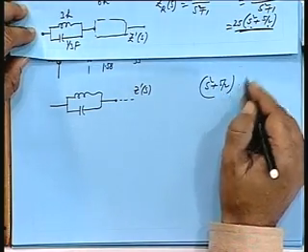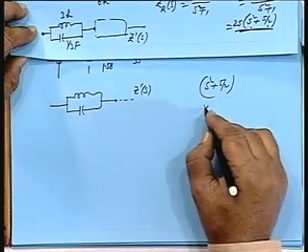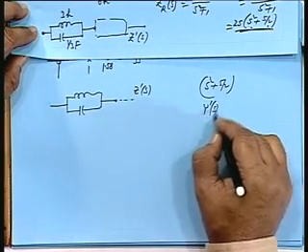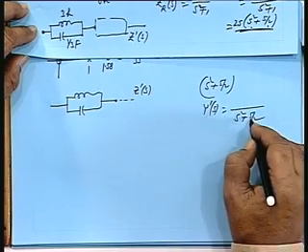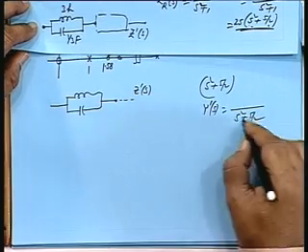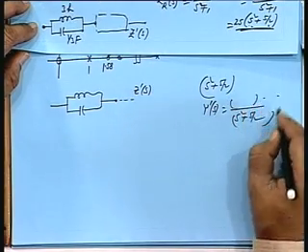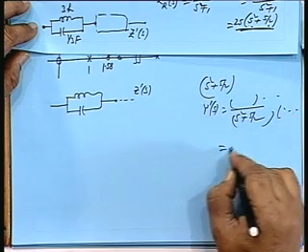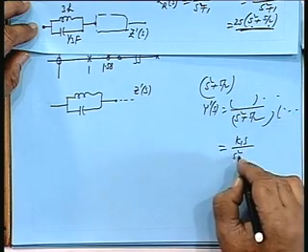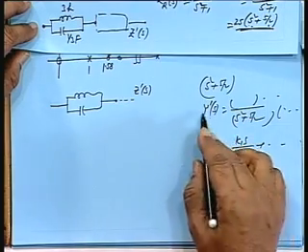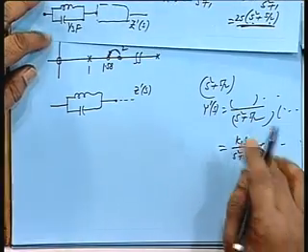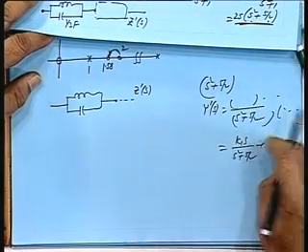Any 0 you convert it to a pole. So, I will take y dashed s, which will give me s square plus 5 by 2 in the denominator. There are other factors, and this one I will write as k1s by s square plus 5 by 2 plus other factors. That means, y dashed, the admittance, is taken as some y1, y2, y3.